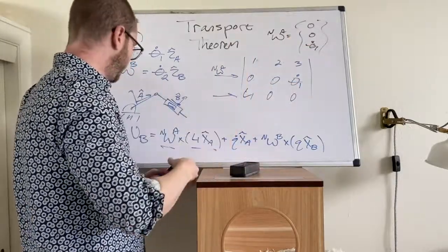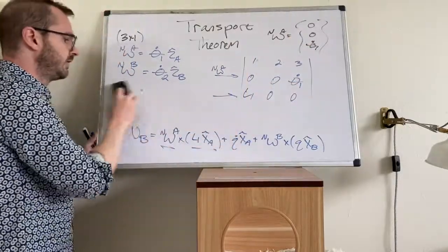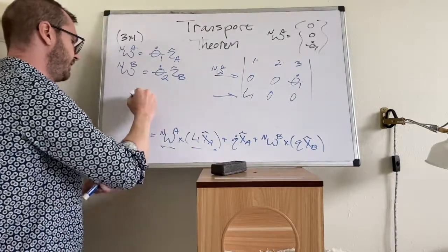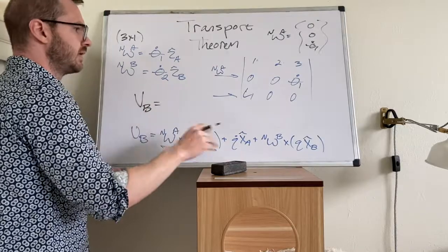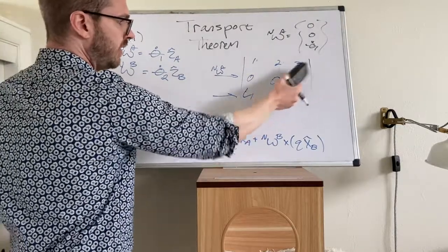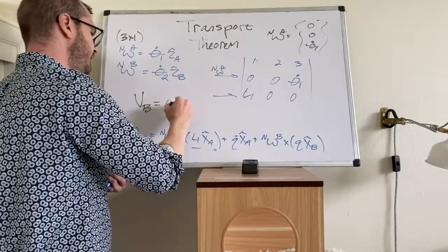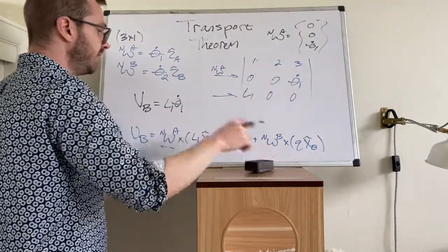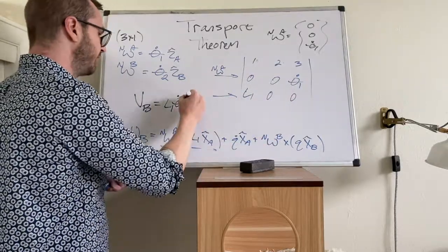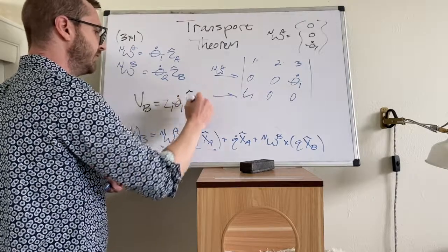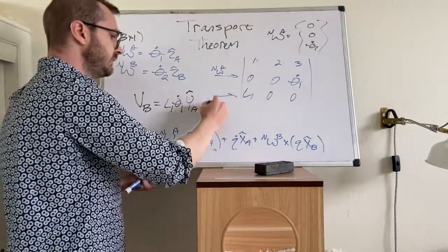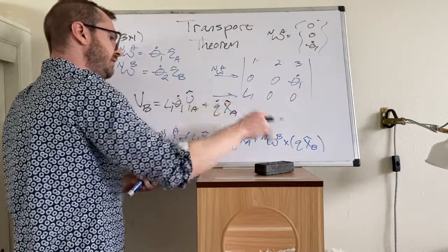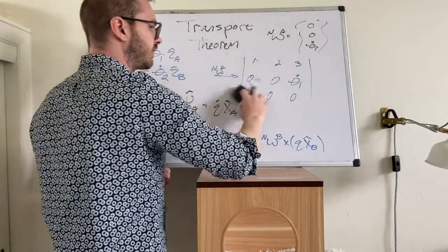So if we resolve this cross product, what we're going to get is, cover this up, and then it's positive L1 theta 1 dot, and that was the Y column, and these quantities are in A frame, so this is the Y hat A direction. I'm going to bring the next one up, q dot X hat A. So that's one way to solve a cross product.